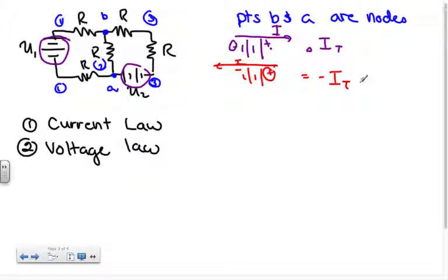So when I'm dictating how this works, the sum of the current going in equals the sum of the current that goes out. So how does this work? In this situation here, I have a current that's coming in here. I'm going to call that I1, because I'm starting from this positive end. And this is the way I usually go. I usually start from the positive end and go this way because that will, as you'll learn, be a positive potential difference.